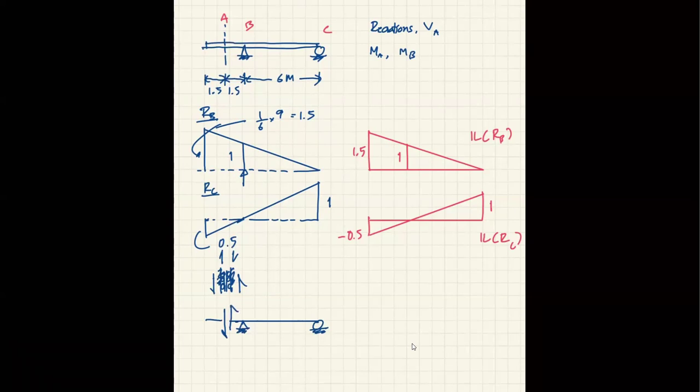You can't just push the beam up because it has 2 vertical reactions. So this will not move. But this will move down freely. So that means your shape is going to look something like this: this guy will fall down freely, but on the right side, nothing moves.